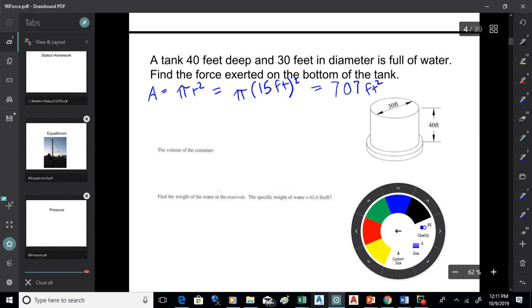You'll get an area, okay? 707, thereabouts. You want to get the depth into that. That gets you the volume. And then multiply that by the weight of water per cubic foot. That's on your formula sheet. And that's one of those numbers, if you do this stuff enough, you probably couldn't even forget if you wanted to.